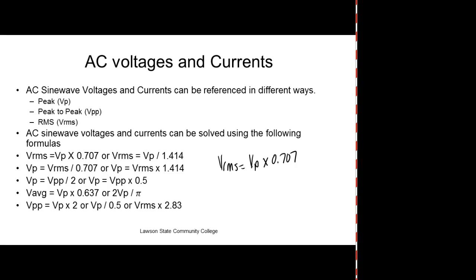Right? What's the meter that you need to buy if you are looking at AC waveforms that are not sine waves? It's called a what type of meter? Huh? We talked about it the other class. Sometimes I think I'm just talking up here. It's called a true RMS meter. It costs a lot of money. You may not understand that, but if you're into variable speed AC drives and stuff like that, then that would be the meter you would buy. If you're dealing with just Alabama Power, then just these guys right here, they're a lot cheaper.